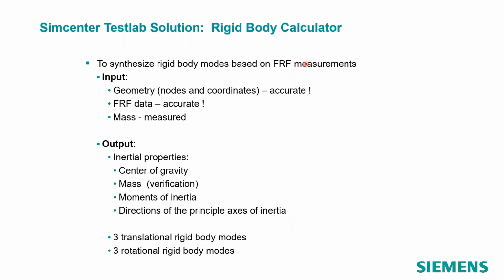We like to use dummy masses to compensate for any mass loading effects. If I put an accelerometer on a structure and put a second accelerometer next to it, and the FRF shifts, then you have mass loading. One way to compensate is to test with all of the accelerometers on at once, and then remove the weight of the mass when we do modification prediction.